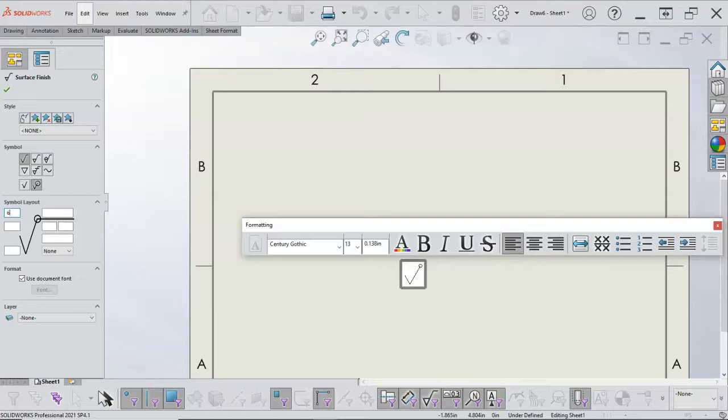So I said 16 or 60, 63, so it goes basically in increments of 8. So 8, 16, 32. For whatever reason, no 64. It goes to 63 and then 128. And 128 is kind of in that saw cut. So a lot of times this will dictate processes as well. The machinist still has to make the decision of how to achieve that finish, but it gives a start for the